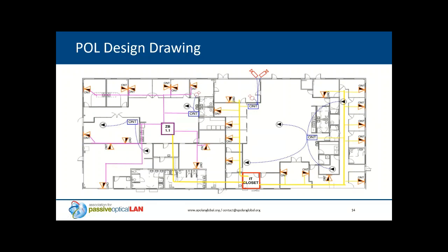All of our ONTs are feeding power over Ethernet, even PoE+. So we're actually powering up these devices. Once you get into putting these ONTs in the ceiling and in remote areas feeding these overhead devices is kind of where you get into more of the remote power. Otherwise, you might need some local AC power in the ceiling.